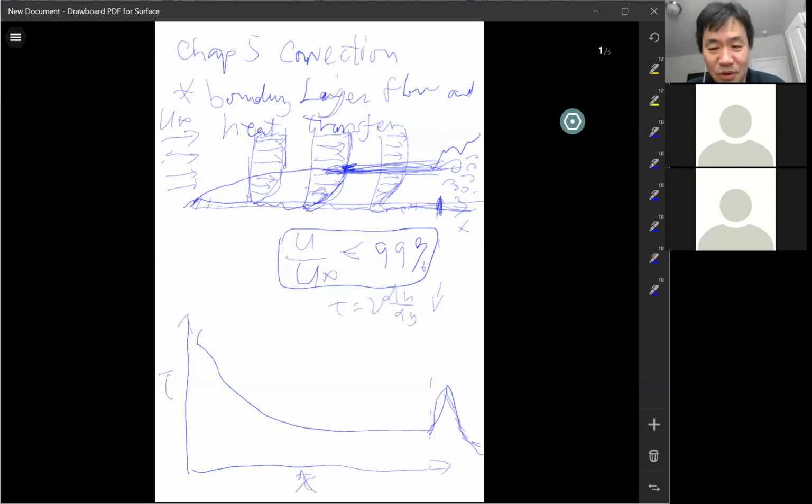That's just an example. So when the flat plate becomes longer, the laminar flow cannot be held anymore, then it becomes turbulent, and the eddies start to generate. Then the shear stress actually eventually decreases compared to the laminar region. So that's something you probably want to remember when you do surface design for heat transfer.